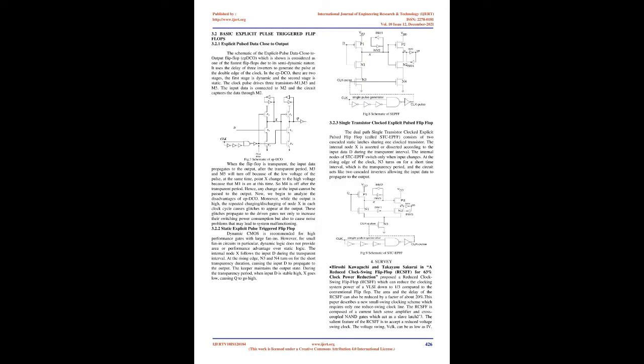For the RCSFF, the D and D-bar input can also be small voltage swing signals. Using these characteristics, the RCSFF can be used to speed up RC delay of long buses. By placing the RCSFF at the end of a long bus and by sense amplifying the slowly changing D input, RC delay can be reduced to 1/3 compared to the conventional F/F.